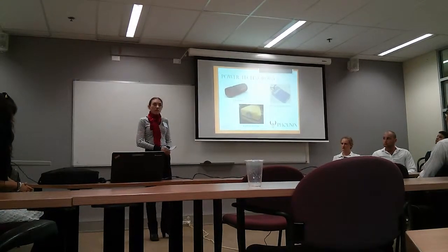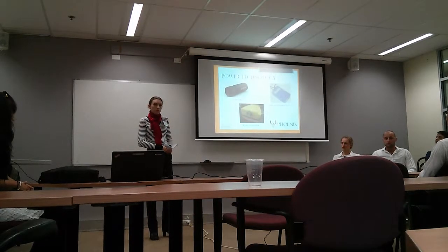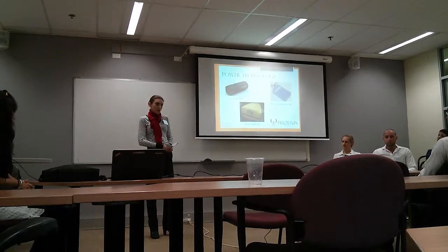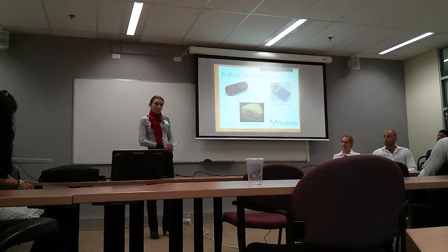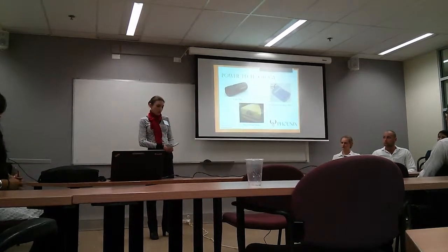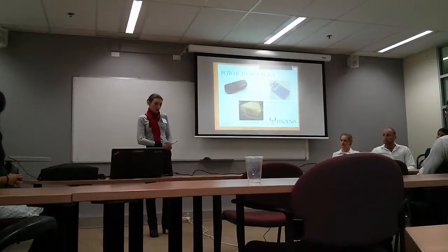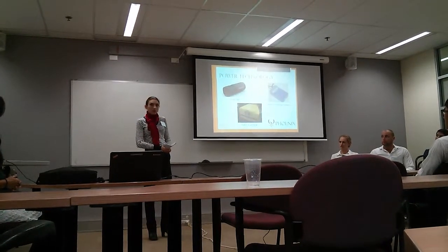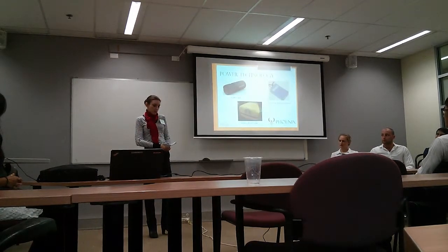The advantages of petrol fuel are the high power density. It's easy to acquire and it's relatively inexpensive. The disadvantages are that you would need much more vibration isolation for the engine, and obviously if you have a petrol engine flying over a bushfire and the UAV crashes, there's a risk to the recovery of the vehicle and any data that it has stored.